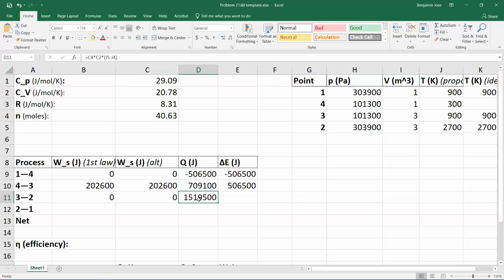So quite a bit of heat is drawn up in this last isochore. And that makes sense because we've shot up from 900 kelvins all the way to 2700 kelvins. It's a big change in temperature and a correspondingly big change in energy that's got to come from the heat. Remember, there's no work being done. So we're not increasing this gas's energy by squeezing it. We're only increasing the energy by dumping heat into it. And just like before, there's no point in me doing n CV delta T here because that's exactly what I did for Q. Let's just recognize that according to the first law, if none of the heat is used as output work, then all of the heat shows up as a change in the thermal energy of the gas.